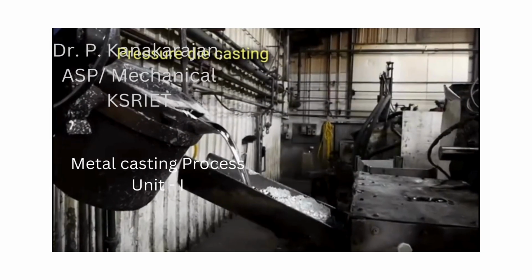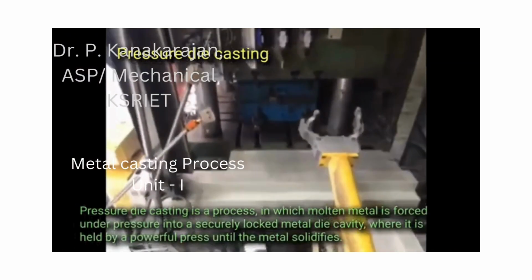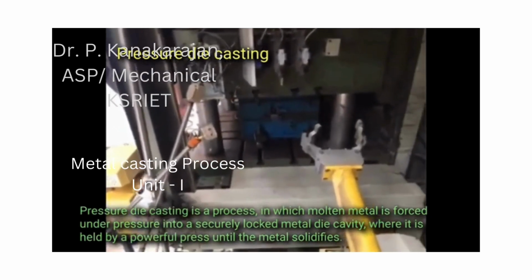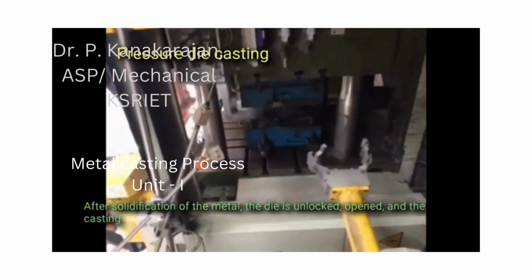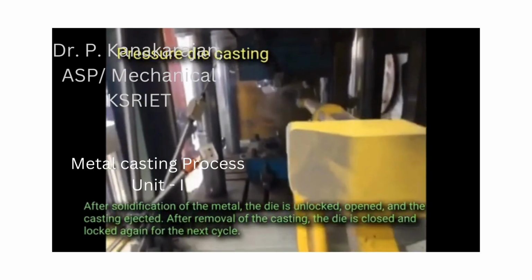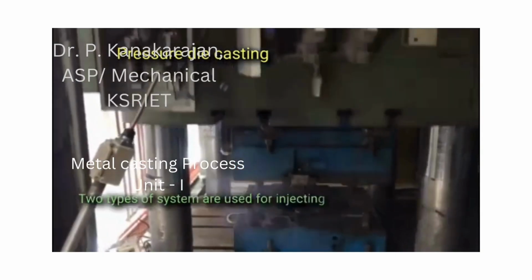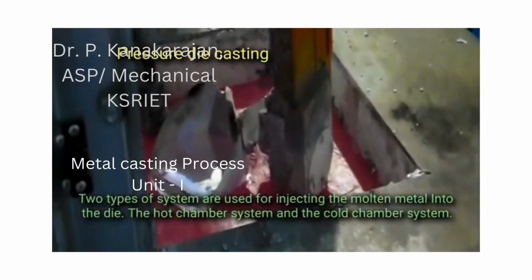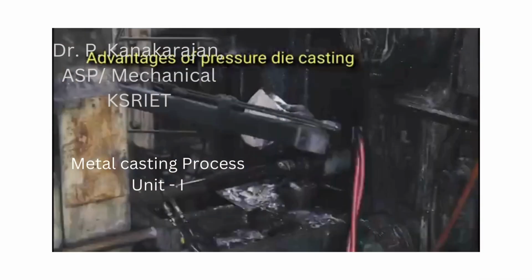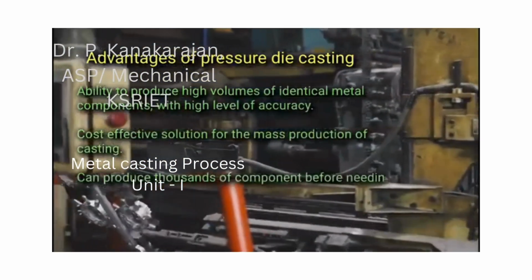Pressure die casting. Pressure die casting is a process in which molten metal is forced under pressure into a securely locked metal die cavity, where it is held by a powerful press until the metal solidifies. After solidification, the die is unlocked, opened, and the casting ejected. After removal of the casting, the die is closed and locked again for the next cycle. Two types of system are used for injecting the molten metal into the die: the hot chamber system and the cold chamber system.